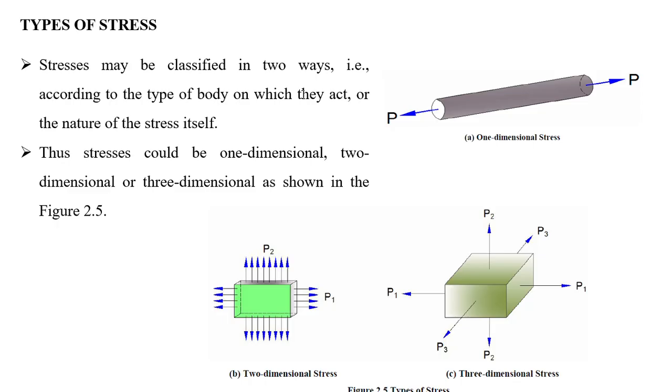In this diagram we can see one directional forces, only axial forces, which can be taken by an axial element, a member carrying only axial forces, like struts or column members. In trusses we can see struts, and those struts carry only axial forces. Their nature may be compressive or tensile.